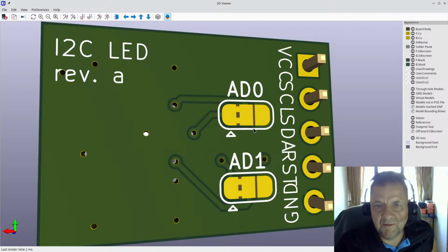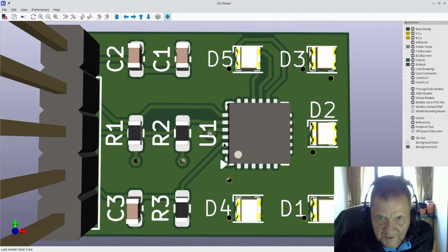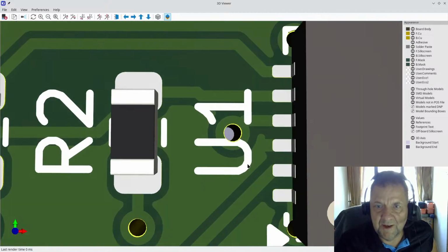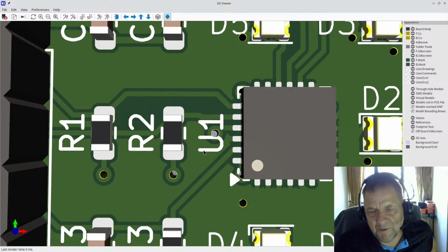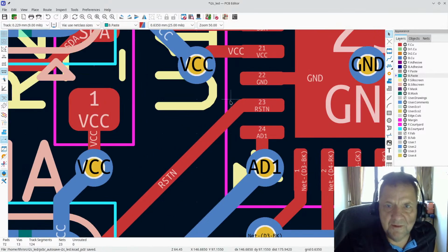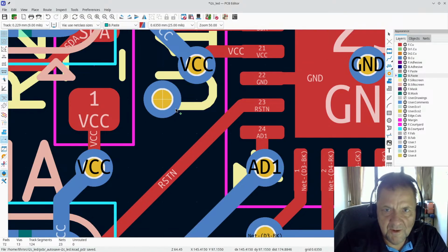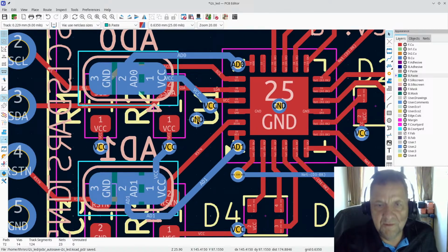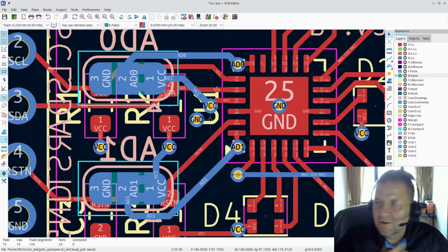So it will get ground up that one, but unless I screwed that up, you also have ground coming in here to this pin directly. I probably need a ground pin over here. Let's do that. So we have ground here just to make sure that this one is well connected. Let's do a ground pin there. Right, so this one will have a very short path down to a good ground.